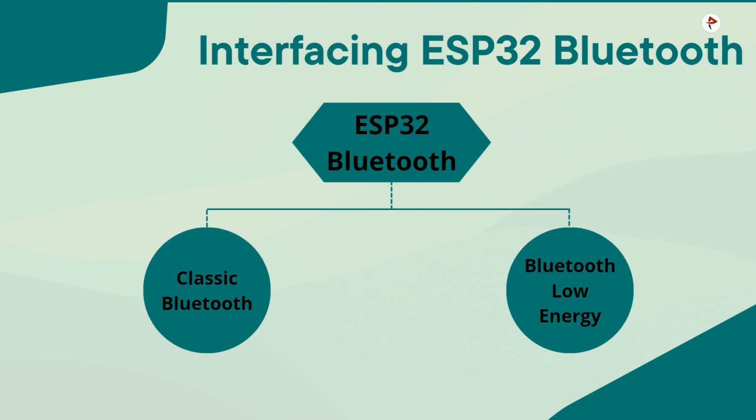The communication between ESP32's processor and Bluetooth controller is based on serial interface. So ESP32 classic Bluetooth serial communication means if you ever worked with Arduino and any Bluetooth devices like HC05, then you might remember that Arduino Uno and HC05 communicate over serial communication. ESP32, which already has a Bluetooth controller, also has a similar communication between the main processor and the Bluetooth